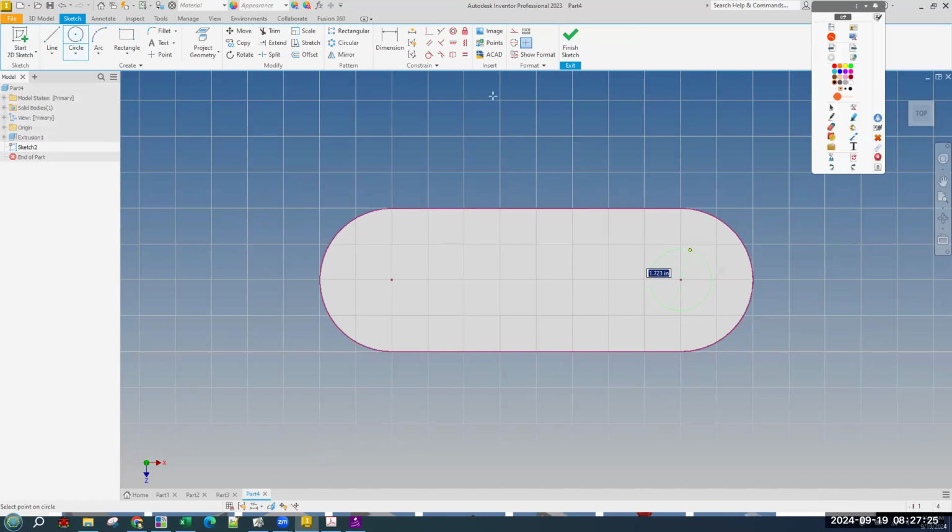So we need one circle over here that is 2-inch diameter. We need another circle, which we can just use a line. Actually, we can just go and do the rectangle here. Rectangle from this top corner to, you'll see, even though my cursor is over here, you can see in the bottom left, if I go so that the height is the same height as the circle, I still get a soft snap there to line up with the circle, which is what I want.